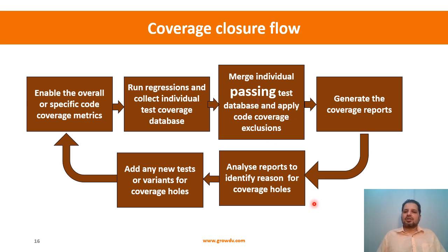And then based on this analysis you might have added additional exclusions, so those all lead to the boosting of the functional coverage number. So you might be at 86 and then it will become 91%, and then you keep on doing that. After 91 it might become 93, 95, and so on and so forth, right? So it's an iterative process with few iterations depending on the complexity. You achieve the convergence, right? So, and once you have achieved the convergence, it may not always be, as we have discussed about it, that it may not naturally hit everything.